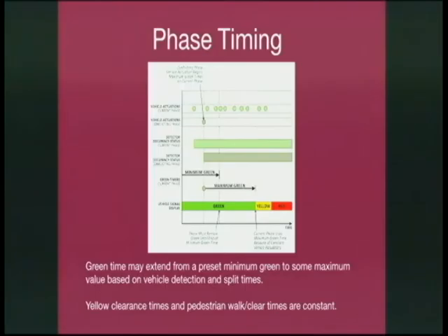Today they're a computer. You have inputs and outputs. You have metal detectors in the roadway or cameras that detect the vehicles. Those are inputs. You push the PED button, that's an input. The outputs, of course, are the different displays that turn on and off. And you have a dedicated controller that's controlling those things. Within that controller, you have different timing that goes on.